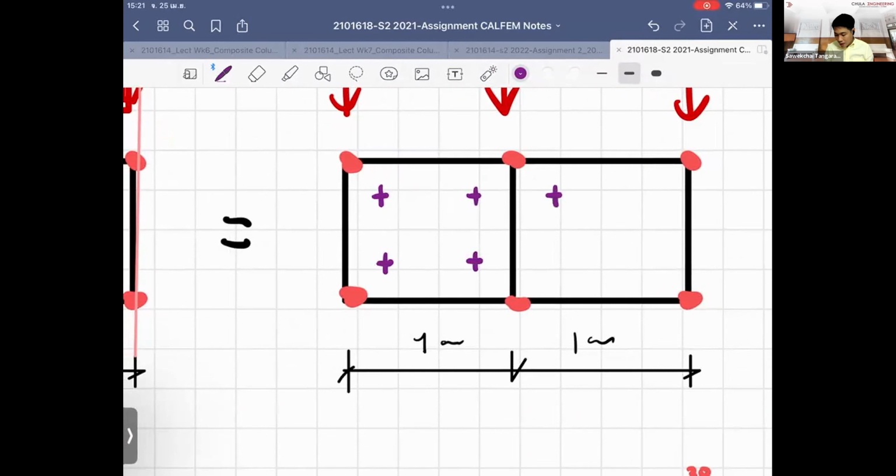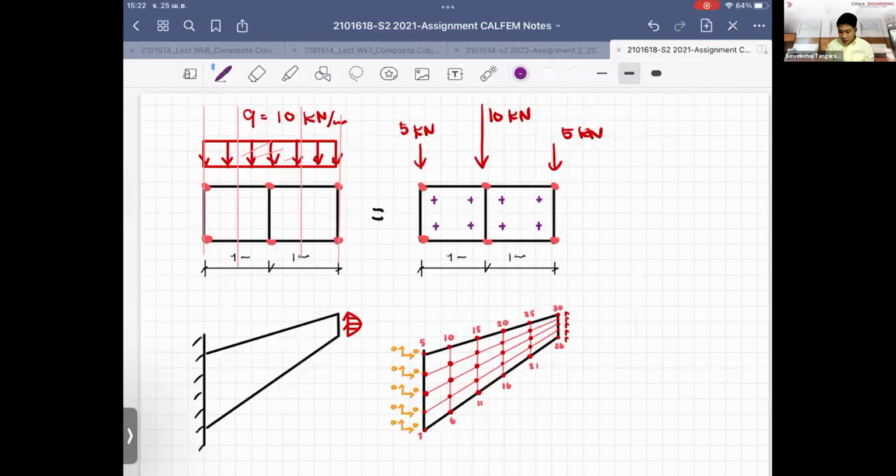So it depends on how you use the numerical integration. What is the meaning of the stress at the Gauss point? It is an approximation. Let me explain to you, and that will lead to how we can make sure that our discretization works or doesn't work. The meaning of the stress at the Gauss point.